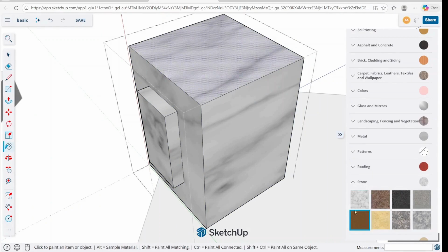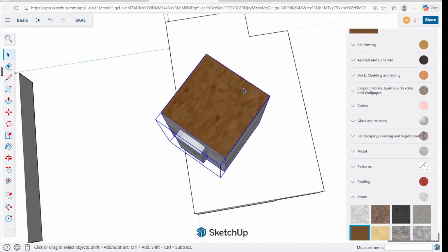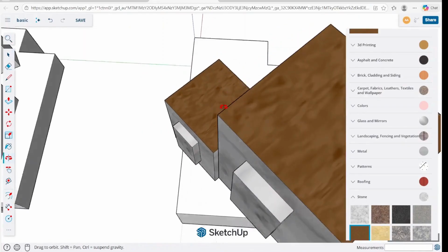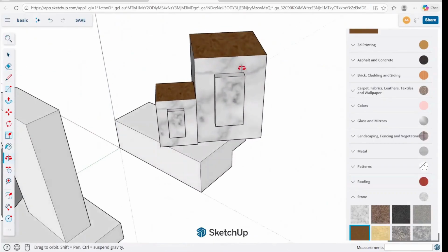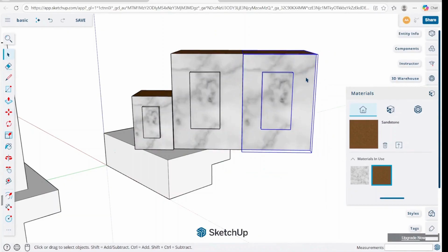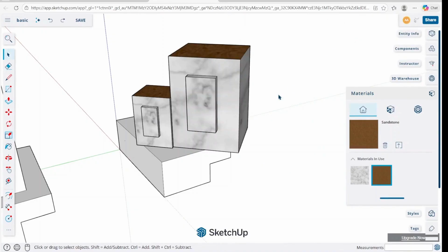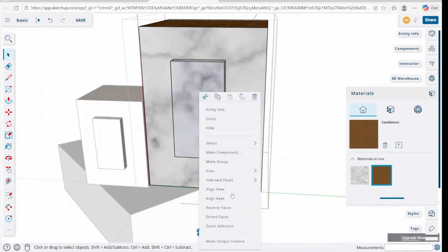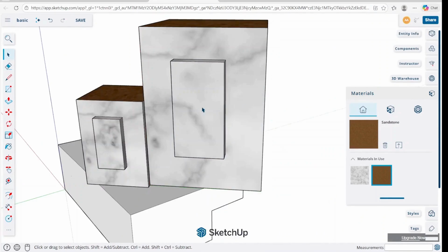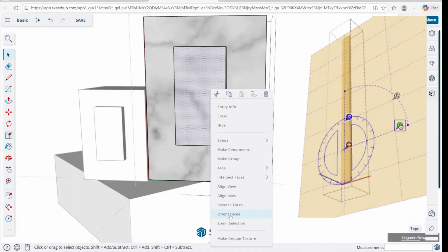You have to double click on the object if you want a different material for the other surfaces. Modifying the material sizes, grain or weaves are not available on a free version, nor changing the direction or orienting the pattern.